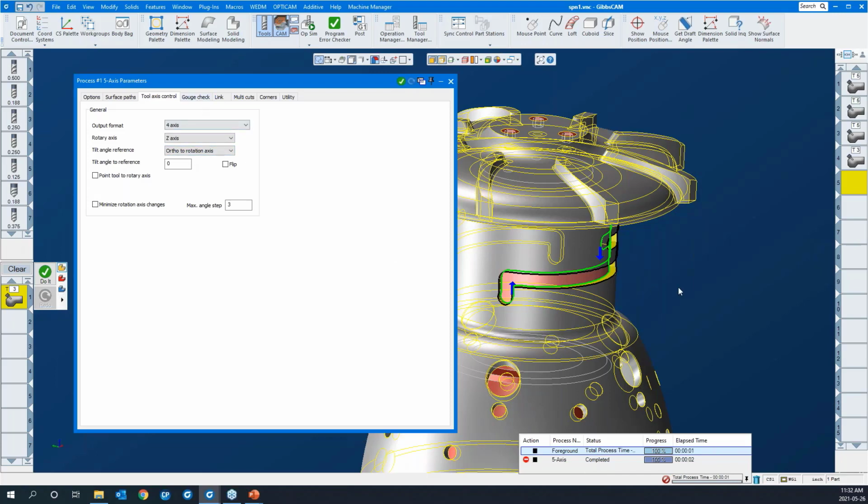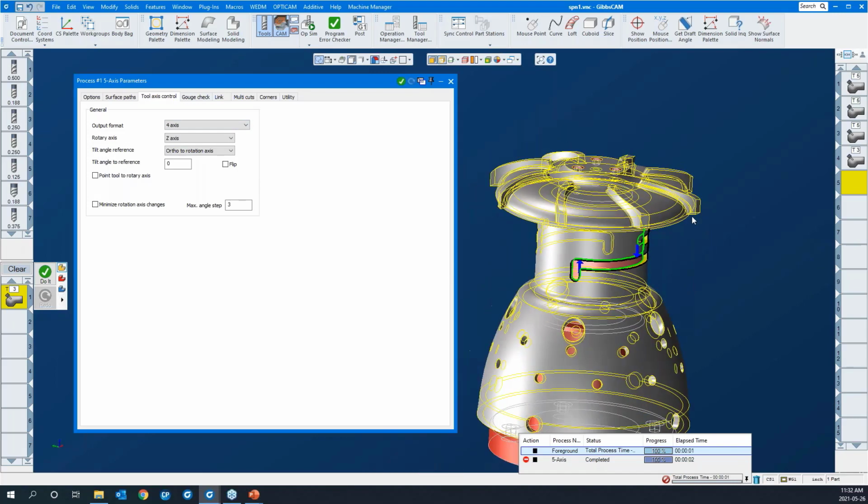Okay, this is going to go off center. Why? That's a big question when you're doing 4-axis milling. Of course, the 5-axis module supports off-center Y machining. If you wanted something more like polar and cylindrical, where the tool always pointed to center, the button for that is right here. If you clicked on that, it wouldn't effectively machine this feature.